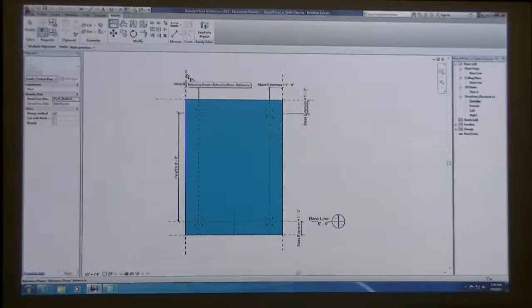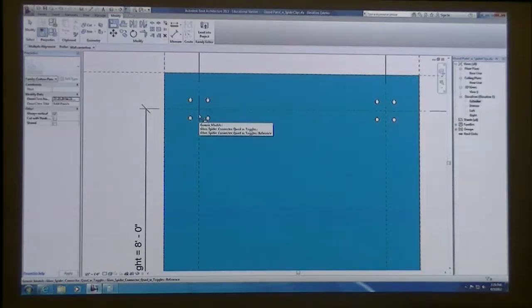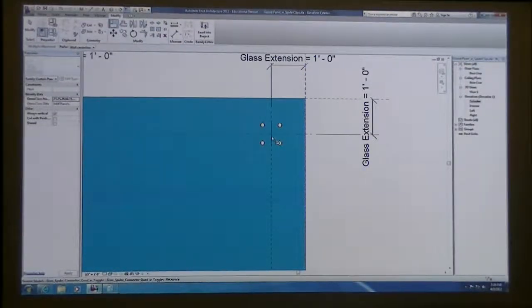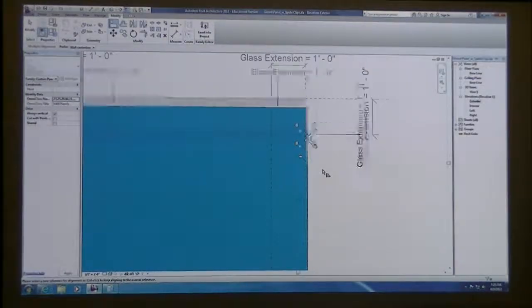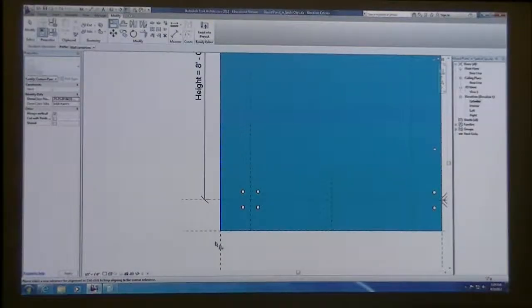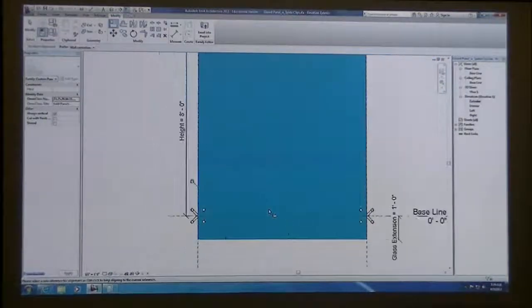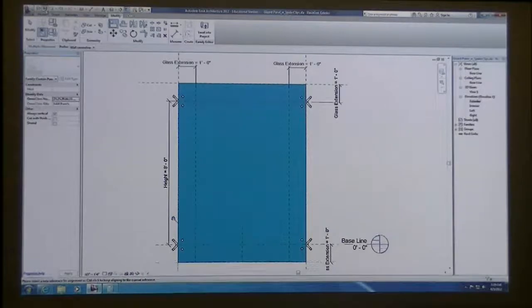If we align the vertical, and you zoom in so that you can only select not the reference line, but the spider clip center line, and again, remove the constraints, unlock it, and do the same thing on the other side. This is the easy one because we don't have to set a parameter to make this work. We'll know that it always works because we're locking it to this reference line that already has a parameter. And I locked it to that reference line as well.